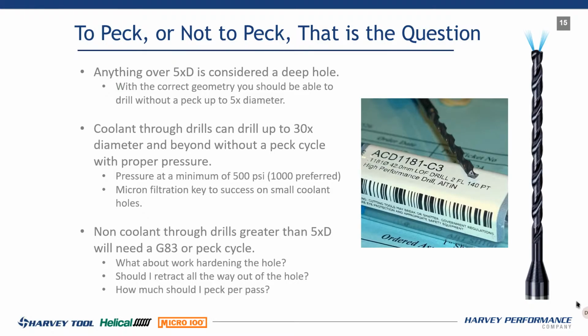Now, there might be some on the call who are listening and going, are you kidding me, man? I just drilled a 3 times D hole and I broke the drill 3 times and I had to peck it. You're right. We're going back to the right geometry, the right material for the right application. But usually, 8 out of 10 times, if you're less than 5 times D and the geometry is right, I'm going to tell you, you don't need a peck cycle.